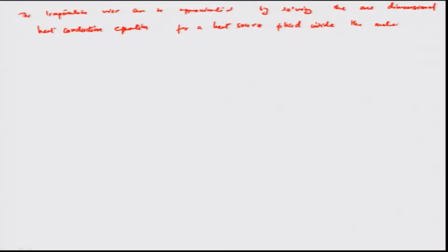In this case, the heat pocket is below the transparent layer, you have to remember that. Okay. So, placed inside the metal. So, if you look at a one dimensional heat conduction problem this way, so you have del theta as a function of z, which is the depth, and time t, by del t, theta is temperature here, is equal to the thermal diffusivity alpha of the material times of del 2 theta by del z2